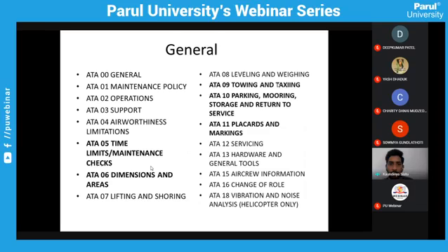Okay, time limitations and maintenance checks are nothing but, if you have ribs in the wing where the fuel is kept, after a certain amount of time, corrosion or erosion can occur. So there is a check to be performed on the skin plates or ribs or plates. So those are all maintained through timely checks. It will be defined in that.